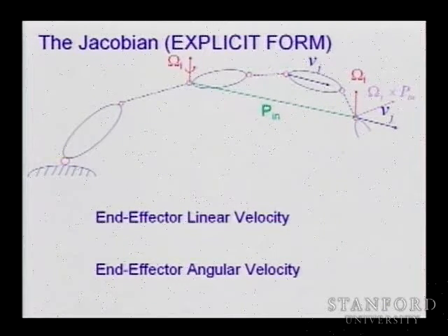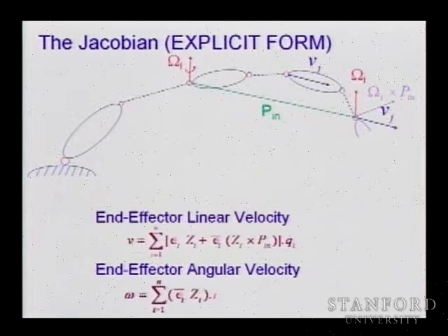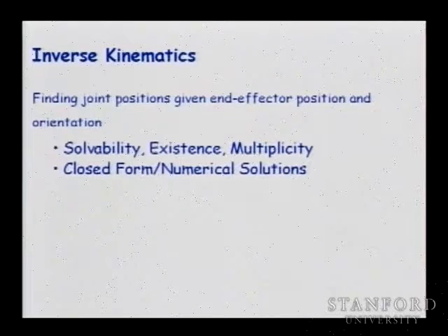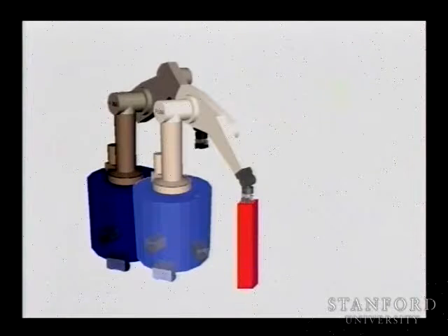So we will also discuss inverse kinematics, although we are not going to use it extensively as it has been done in industrial robotics. We will examine inverse kinematics and look at the difficulties in terms of the multiplicity of solutions and the existence of those solutions, and examine different techniques for finding those solutions. So again, inverse kinematics is how I can find the configuration that corresponds to the desired end effector position and orientation.